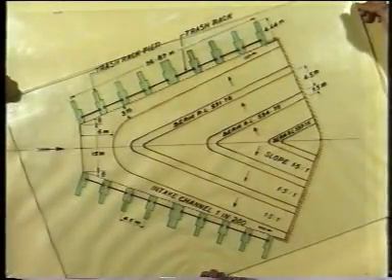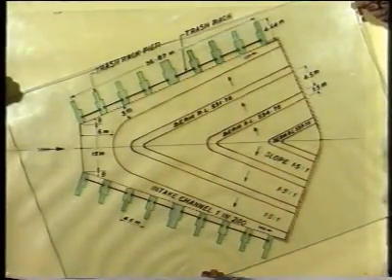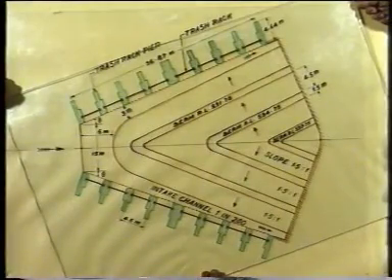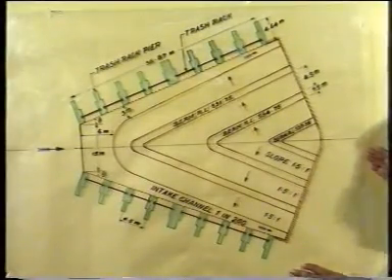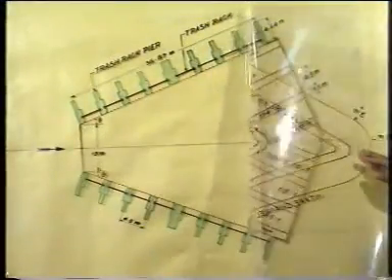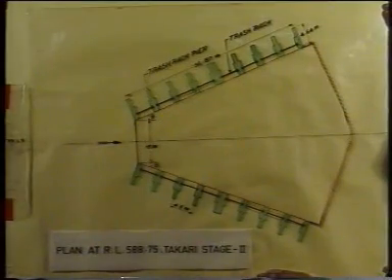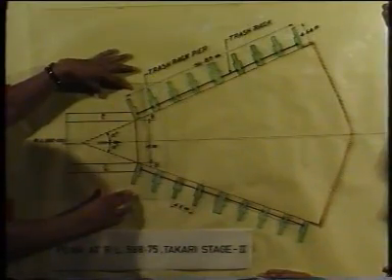Original proposal included the retention of central earth mound and by providing two channels with two berms of 1.5 meters and three slopes of 1.5:1. But as per the revised suggestion of Maharashtra Irrigation Department, this central portion is removed and the forebay level is maintained at 588.75. The central angle between the two pump houses is now 30 degrees.